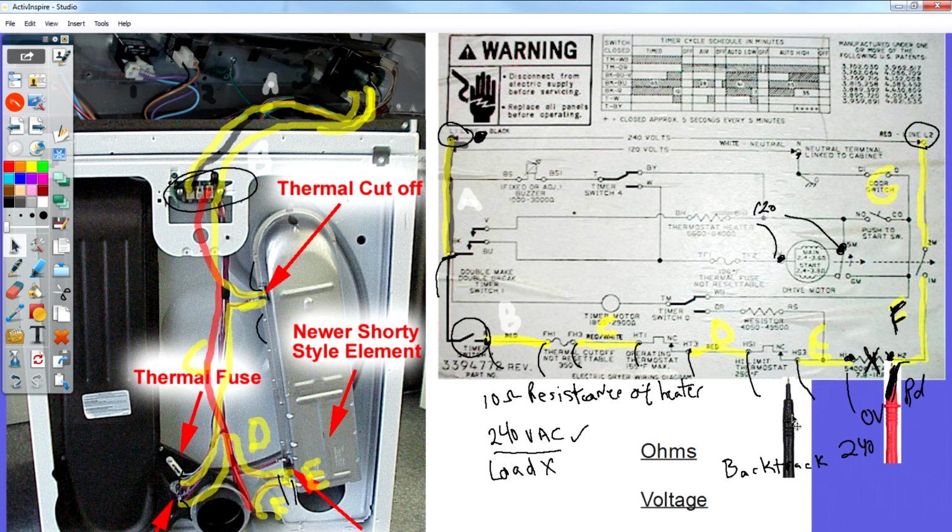Now when I go here and backtrack, now I'm going across a thermostat. If the thermostat was faulty, one side of the thermostat would give me voltage, and the other side of the thermostat would give me 0 volts if the thermostat was bad. And now I've checked the thermostat. I'm going to jump across the wire. I'm checking a wire. Now I'm checking the next thermostat.